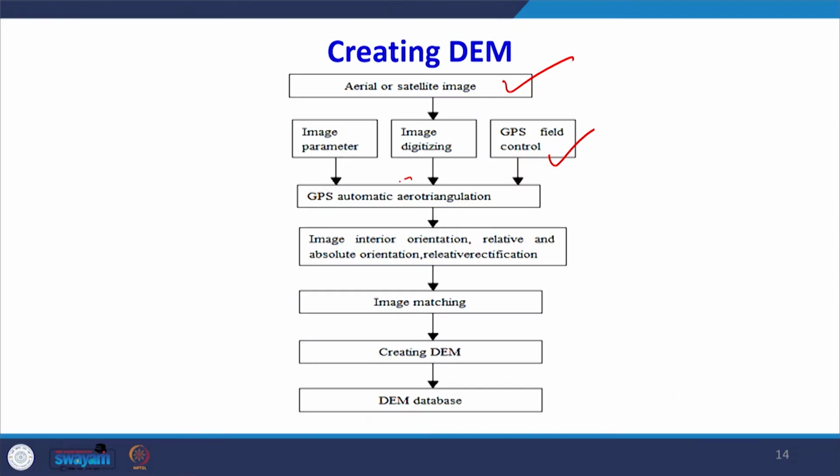So similarly here there are certain control points required so that we can take the elevation of that and create the DEM, and also there are certain control points which are for cross checking the area. So we are using triangulation principle, and when we are using it in photogrammetry it is called the aerial triangulation principle. So we are using that principle.